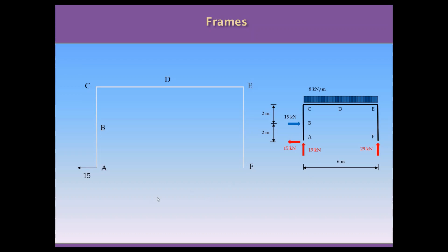15 kilonewton we have at that point. The horizontal force will be the shear force for the cross sections that are horizontal in this column from A. So the first force is 15. The shear force will be constant from A to B and will close with the load applied to the structure of 50 kilonewtons.